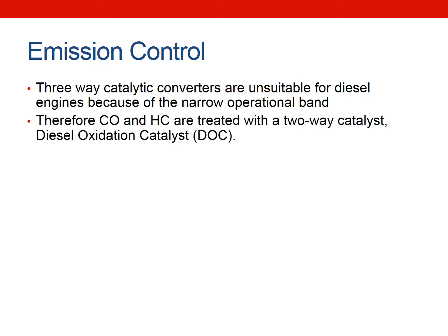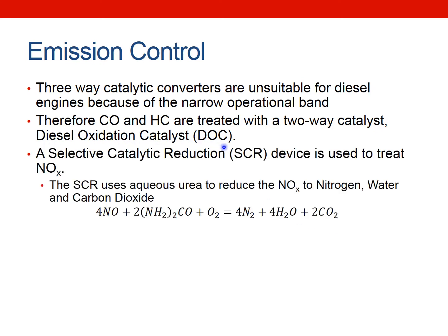So therefore, diesel engines just run with a two-way catalyst, or a so-called diesel oxidation catalyst. So the NOx has to be done in another way. And one technology that's becoming more and more common, started off in heavy diesels and now making it into the passenger market, is what's called an SCR, or selective catalytic reduction device. And this is used to treat the NOx.